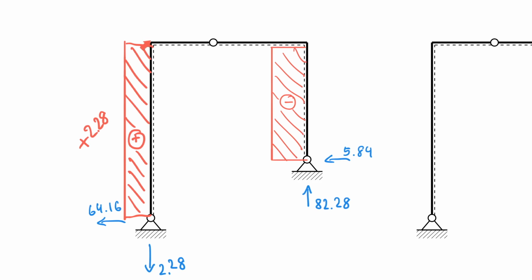So now we need forces that push this to the side, or that actually push along the axis of this member. And I guess the easier one to start with is using the force down here. If I were to make a cut here at the system up here, you can include all this and bring your internal forces here. But what you would find is that your normal force is only affected by the 5.84. And so that doesn't change anywhere to here, and it also doesn't change anywhere here, because remember, you only had a distributed force up here and nothing else.